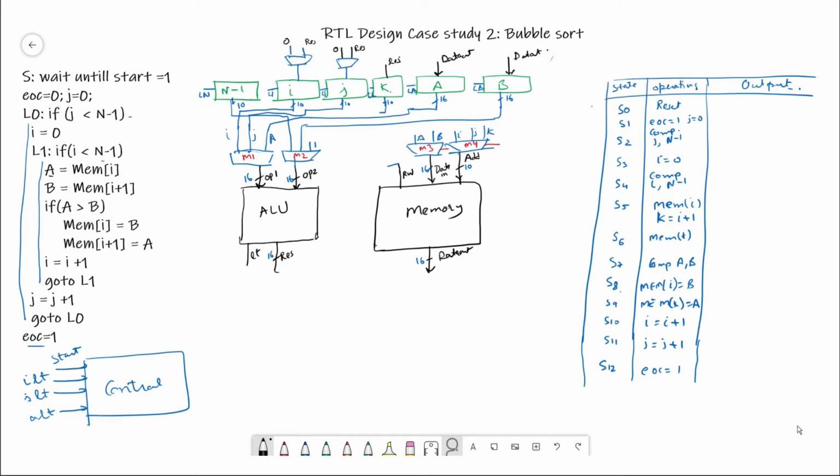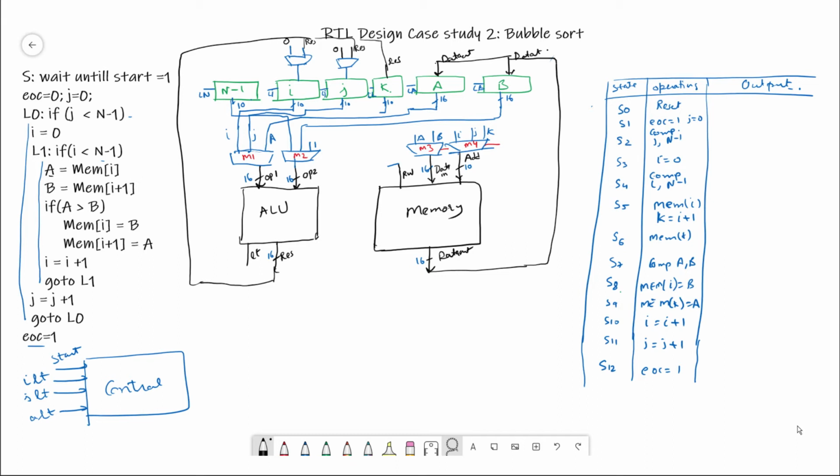Good. So far so good. Basically this is how these connections would be made. This data out value will reach here as well as here, and this result of the ALU will be connected here, here as well as here. And like these mux 4 muxes, let's have these muxes also labeled as M5, M6.